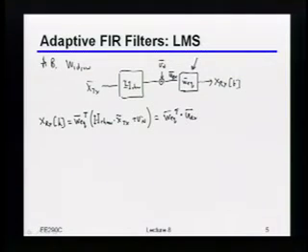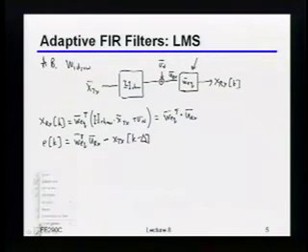But basically, if I wanted to figure out some sort of error signal at this particular sample, that error signal is essentially after the equalizer, that's just a reminder, that's just u_RX. My error signal is just that minus whatever I happen to transmit at some time, and actually this isn't a vector, this is now a scalar, at some time delta samples ago. Because assuming that there's some delay in this channel, you just want to handle whatever that delay is. Okay? So that would be my error.